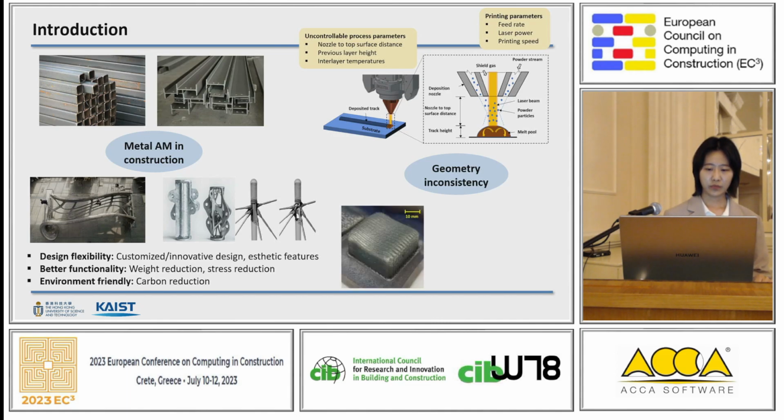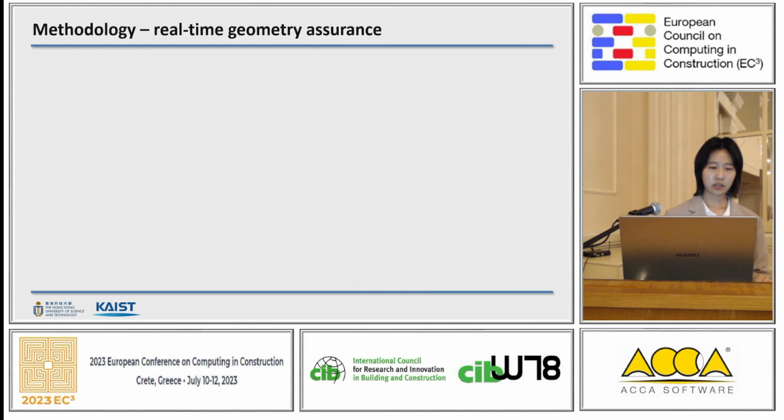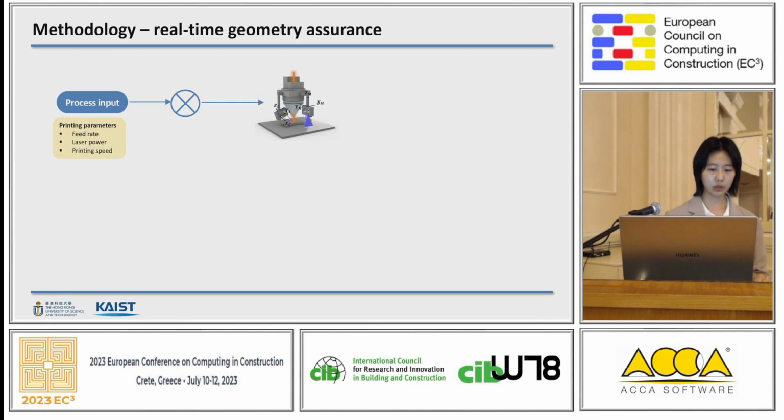So often failure cases will occur, and geometry inspection after manufacturing is too late. It cannot inspect the geometry defects, and even if it can detect them, it is hard to compensate or repair. So in this research, we propose a real-time geometry assurance methodology to inspect the geometry defects during the DED printing process.